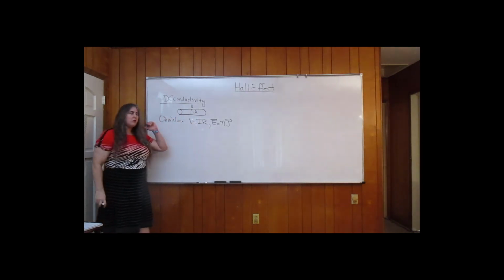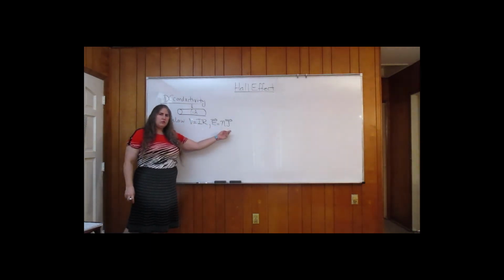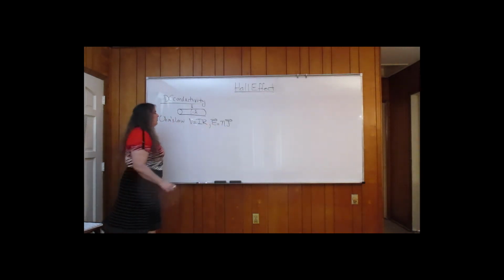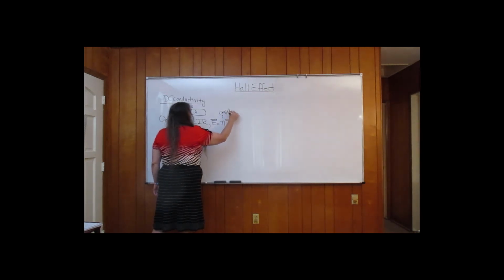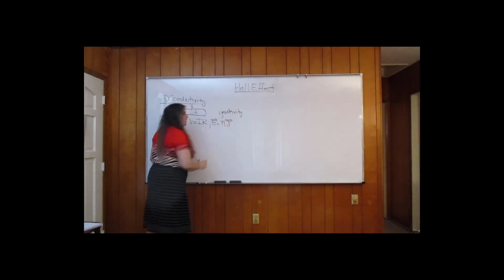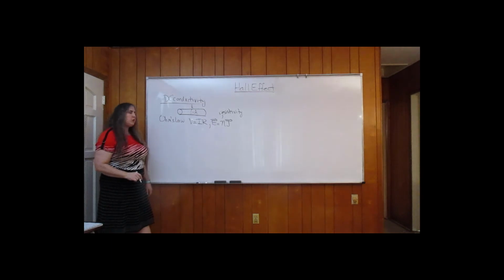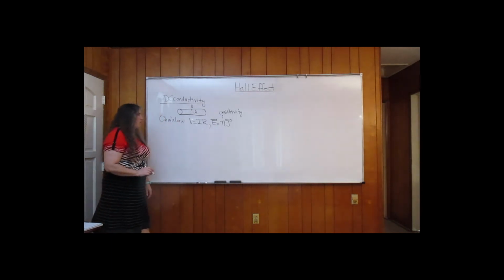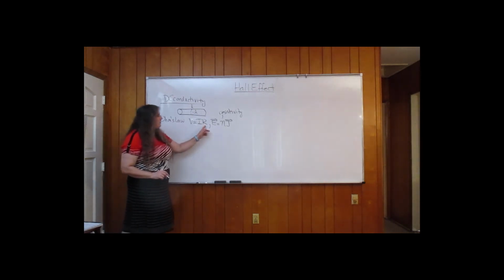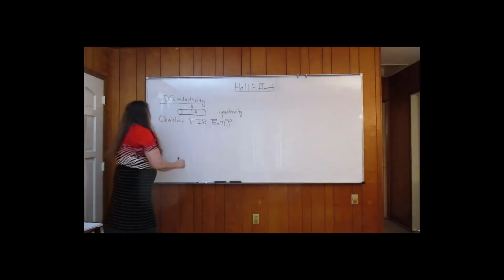Another less familiar form relates the electric field to the current density. So the electric field is equal to the resistivity times the current density, and I am using the Greek letter eta for resistivity. Do be aware that many authors, maybe most, use the character rho. I want to relate the resistance to the resistivity.